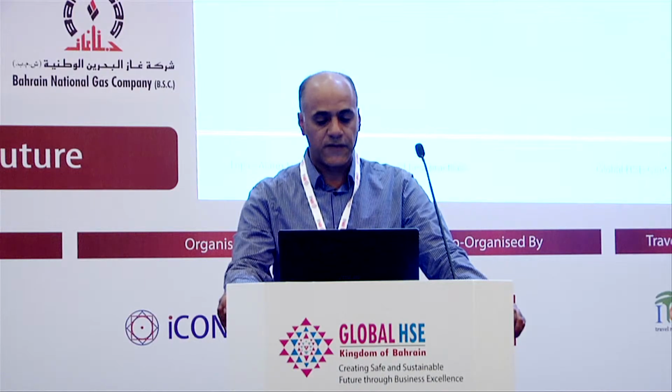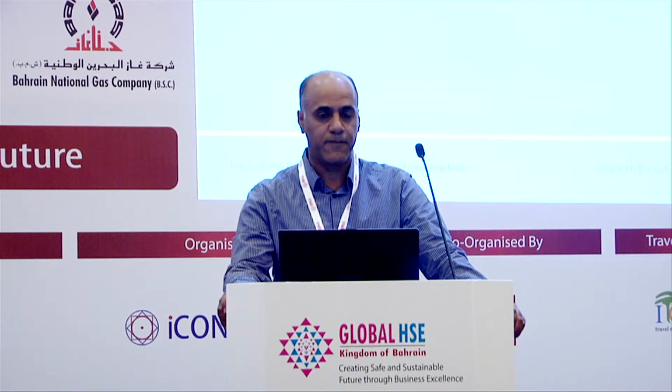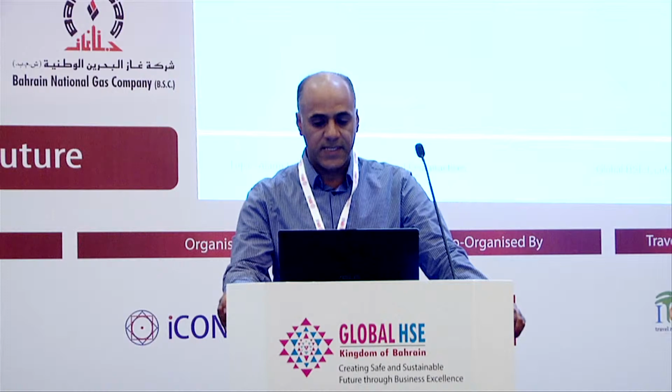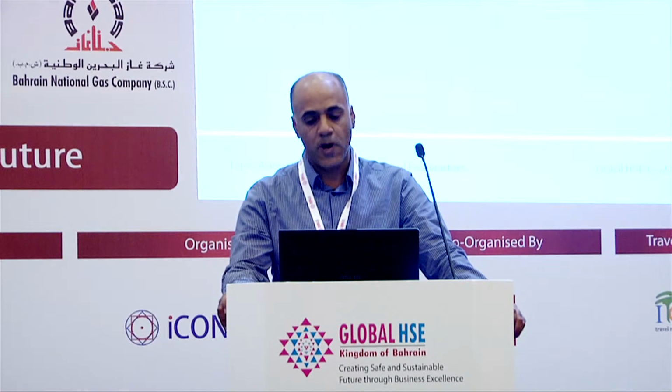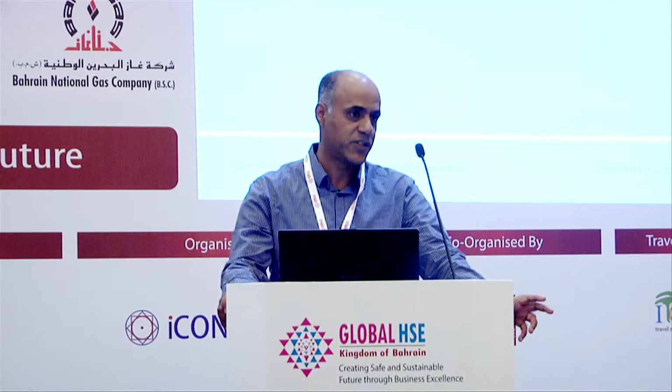The definition itself sets the main 3 parts for any signal to be considered an alarm. It first says that the alarm should have an audible and visible indication, which relates to how the alarm is presented to the operator. Then the operator is the target audience, so it has to be something the operator can react to. And third, it requires a timely response. So we are not supposed to present information to operators where they are not supposed to take action.